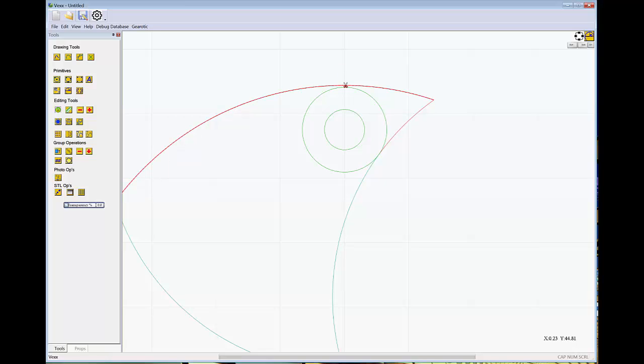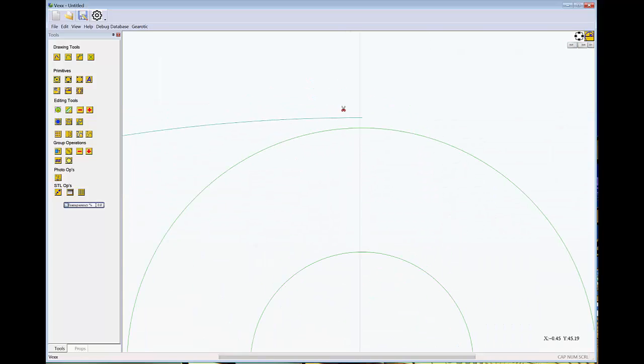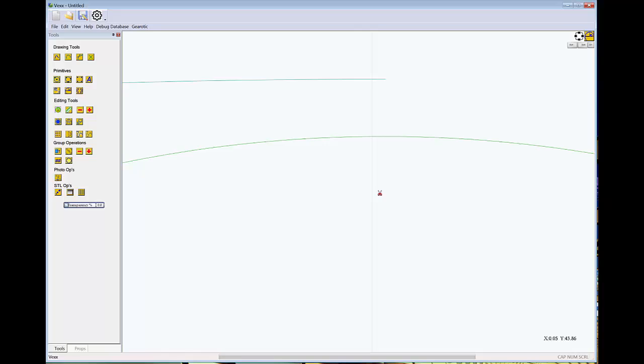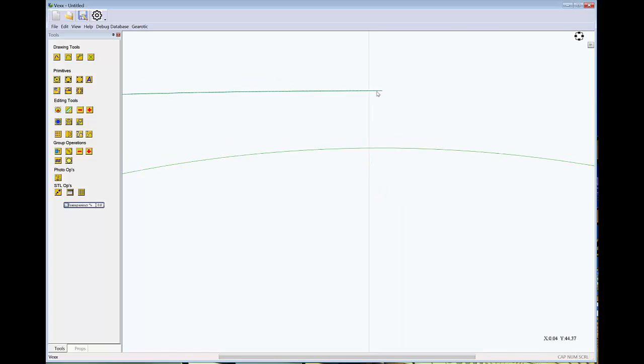So again, we'll use our trick of putting the scissors where we wish and then hitting the left Shift key, and it will remove the appropriate portion. I can now go up and zoom in, hit Escape to get rid of my scissor tool, and move this down to an intersection point. And you can see that the circle glows green when you are on the intersection point.